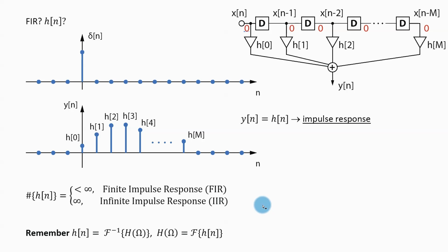Now, an important thing to remember is that this is not just a play with numbers. This impulse response is not just a bunch of meaningless numbers, but it is related to that filtering in the spectral domain. So it is important to remember how this impulse response is related to the frequency response, because the frequency response characterizes that filter. It tells us which frequencies are amplified, which frequencies are suppressed, and what kind of phase shift we can have in that filter.